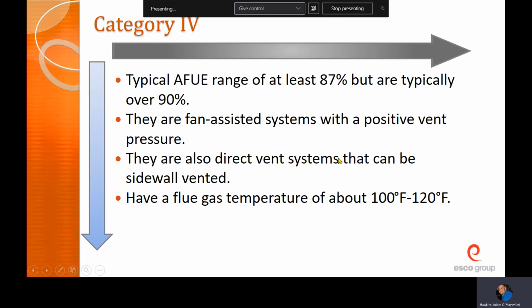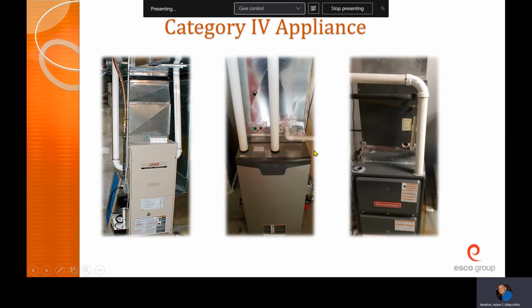I would invest in a good furnace because not only is it going to be more efficient on gas, but if you upgrade your furnace, you're maybe talking ECM variable speed type blowers, which is going to help you in cooling as well. So you might see that savings more year round than with an air conditioner that's only running half the year. You can run a furnace with a heat pump, but normally you don't see it a lot. So usually I'm just talking about an AC and furnace setup.